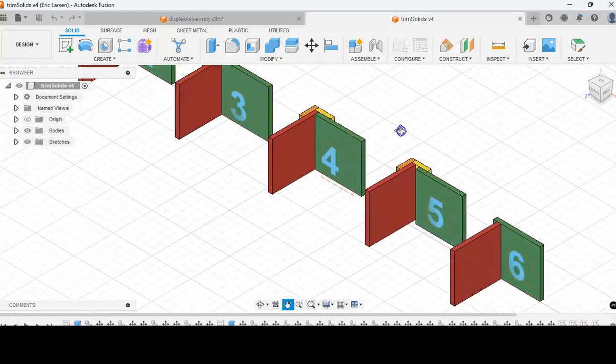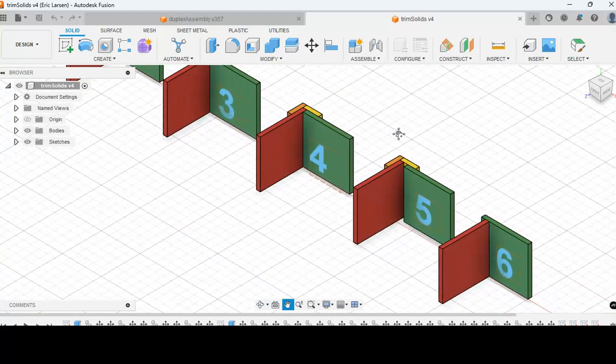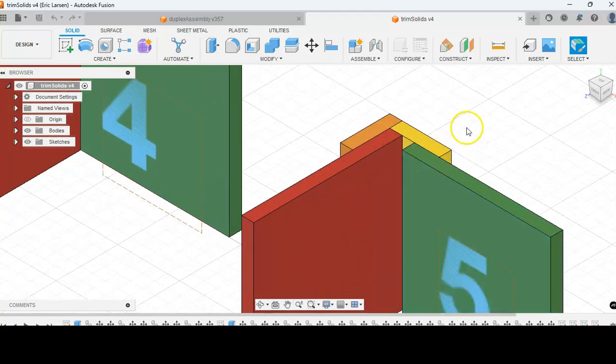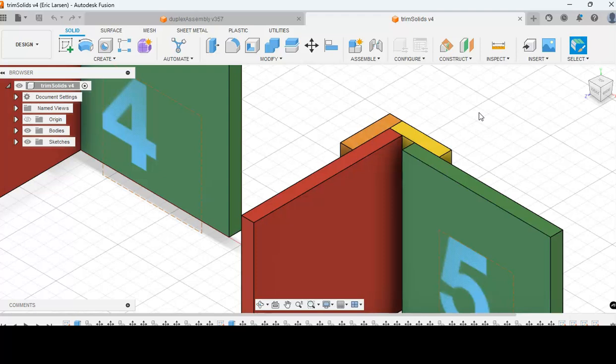Now 5 is an example of what I would call an ugly corner, because you've got a gap here, and this is what you might get if you have some slapdash carpenters. But you can handle that, and as long as this gap is not too large, maybe only 1/8 of an inch, I would personally say that I could live with that, and it's perfectly good because your trim covers up that gap.